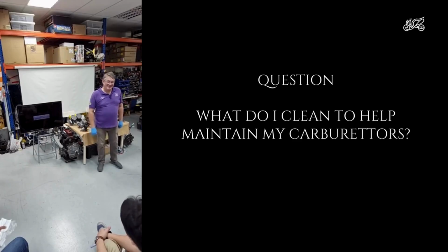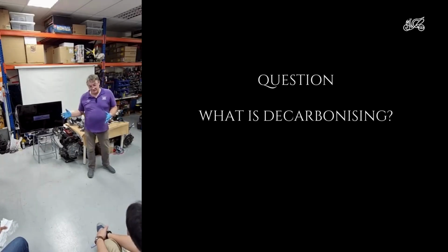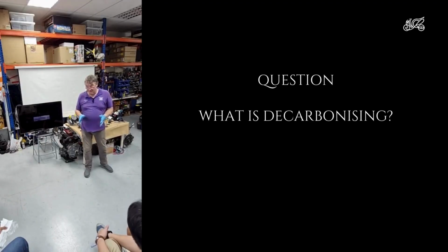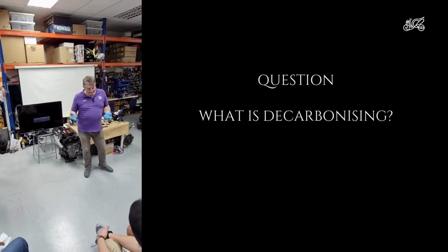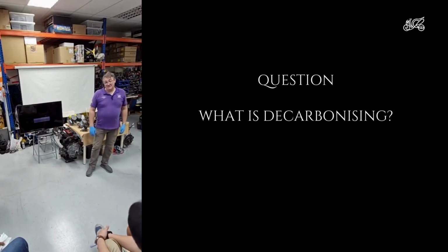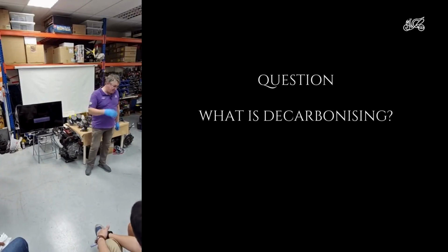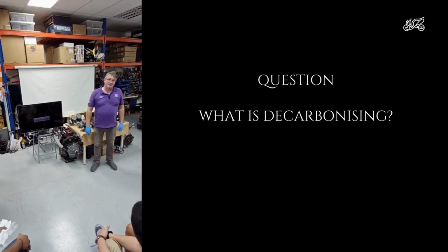The term decarbonizing is... Okay, so if you go back a long time, if you go back to the 1950s, my father talks about, even on a long journey, stopping at the side of the road, removing the cylinder head, cleaning the head and the valves, putting it back on and continuing. So the carbon buildup on old engines was so bad that eventually they would choke themselves up and stop, and you would have to clean it up. Okay, modern fuels have got additives to try and stop that happening. But again, the best thing to do is just drive it hard, and all that stuff will go out the exhaust.